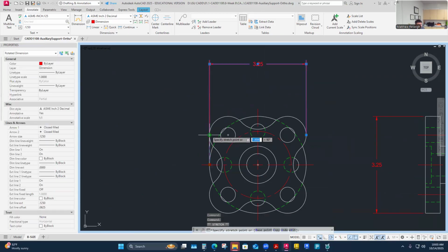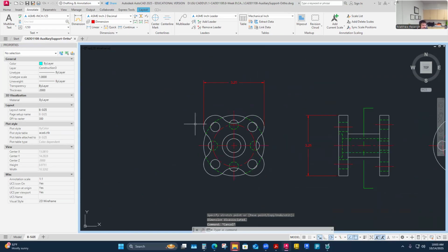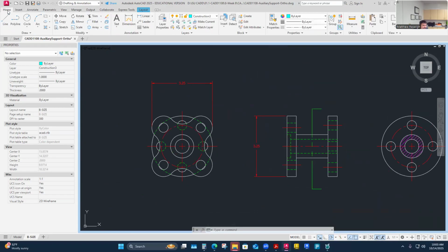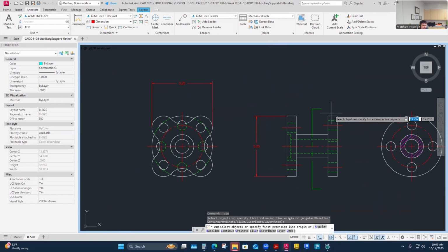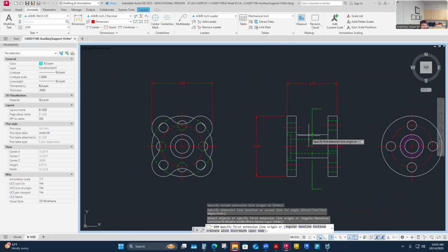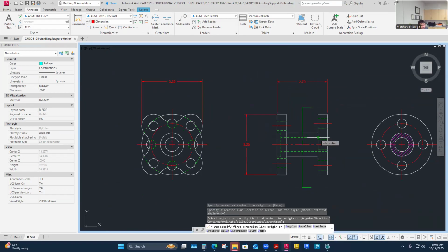I don't know if I'm going to keep this, but the dimensions I want to know are an overall width, an overall height, and then an overall depth. Obviously, the only place it's going to show my overall depth is in the right side view. This one has my overall depth of 2.7. So that captures my three overalls.